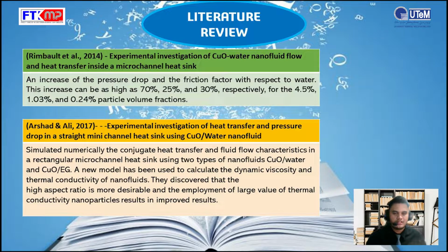It states that there is an increase of the pressure drop and the friction factor with respect to water. This increase can be as high as 70%, 25%, and 30% respectively for the 4.5%, 1.03% and 0.2% particle volume fractions.